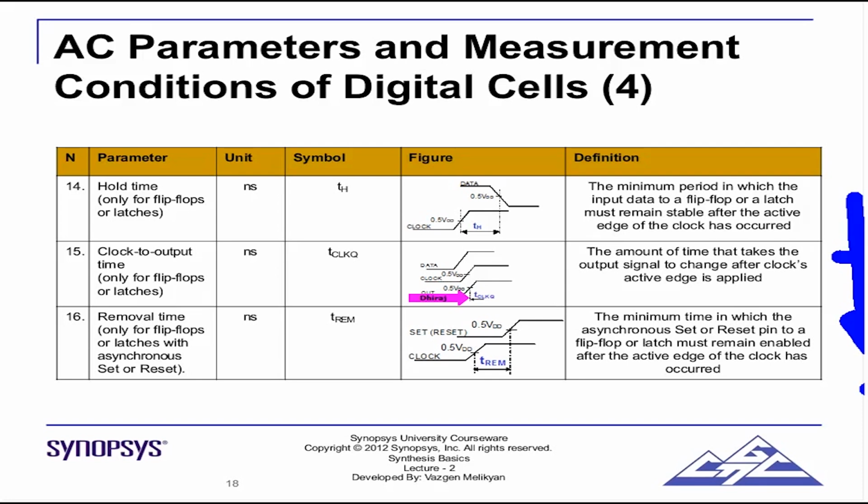Now there are two very specific timing constraints for flip-flops or latches with asynchronous set or reset. A synchronous set or reset is exactly the same as data, because the data pin is also synchronous. A synchronous set and reset behaves exactly the same as data. For example, a flip-flop has the data pin and a synchronous reset. The synchronous reset will have its own setup and hold time constraints, very similar to the data pin.